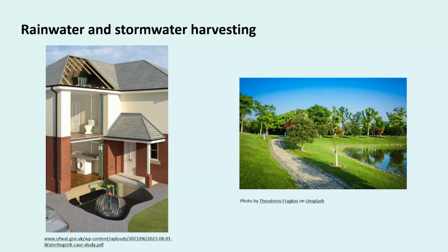So the non-potable demand of 28.5 litres per person per day could also be met through property level rainwater harvesting systems, which could collect, store, and treat rainwater for use in the house. Assessment would be required of the rainfall frequency, the rainfall depth, intensity, and the roof area to determine whether the non-potable demand could be consistently met throughout the year. And given the limited roof surface area available for collection and the lower rainfall in drier parts of the country, which is of course where water scarcity and water neutrality are most acute, this may not always be possible.